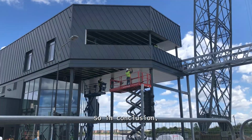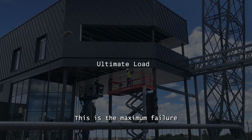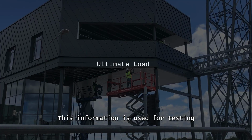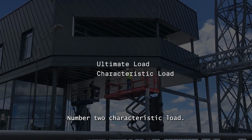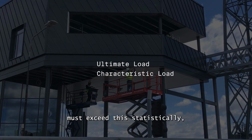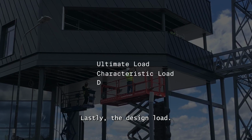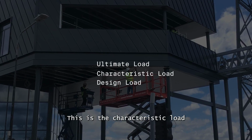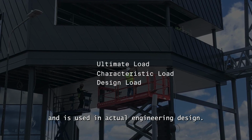So in conclusion, the three load types are: number one, the ultimate load. This is the maximum failure load in a test. This information is used for testing and data collection. Number two, characteristic load. This is where 95% of the tests must exceed this statistically, and it's used for specification sheets and standardized values. Lastly, the design load. This is the characteristic load divided by a safety factor and is used in actual engineering design.